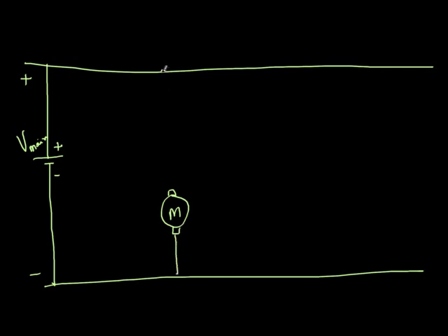Now, in order to measure the current going into the motor, I connect an ammeter here. This motor also requires a field winding, so I am connecting a field winding here. Again, in order to measure the current in the field winding, I have this. Also, I would like to be able to control the field winding current, which is why I have introduced a variable resistor. By changing this variable resistor, you see this branch is completely independent and has the voltage V main. So if I increase this resistance, the current will decrease. That way I am able to control the current.